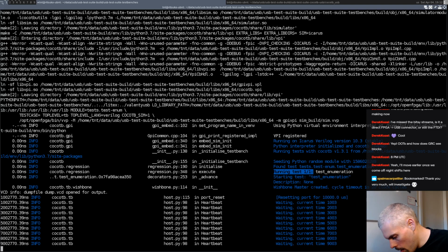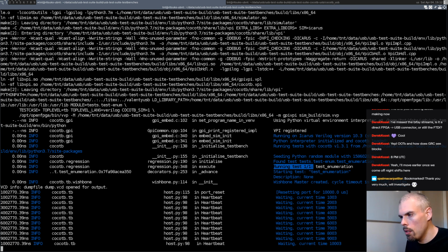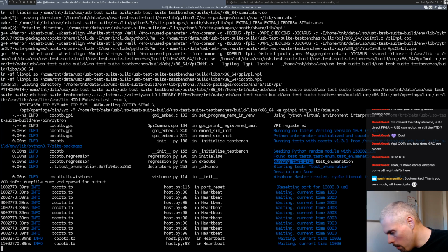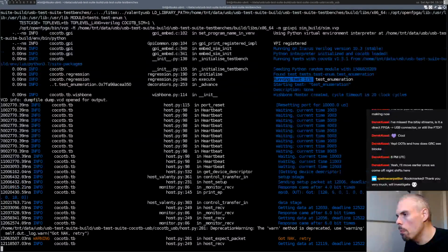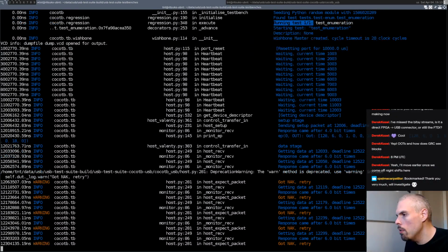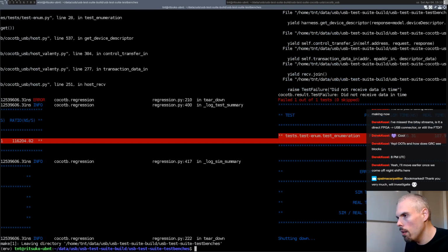I thought at first there was no difference except design for manufacturing and reliability and stuff like that. But actually, on the Hacker version, the flash is not wired for quad SPI operation. Only 2 of the data lines are connected.